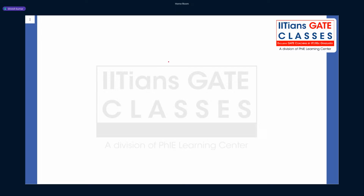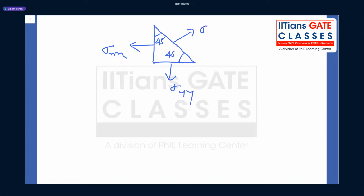What you need to understand is they have given one triangular element. If this angle is 45 degrees, we know this is also 45 degrees. Here they have given sigma xx and sigma yy, and the corresponding shear stress they have given 0. Now guys, we know from our understanding of the concept, the corresponding normal stress is sigma s and this is tau st. Yes or no? Is this clear? Because we have done this triangular element, right? When this angle is theta, this angle is theta, right? This is sigma s and corresponding tau st. Yes or no?